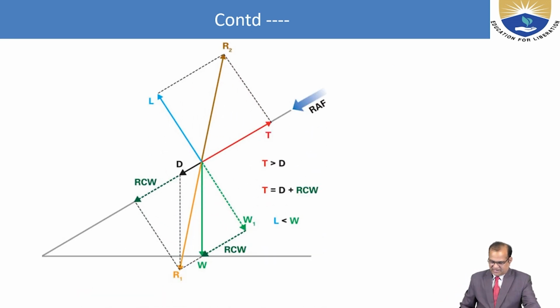Very clear. This slide shows this is your gamma here. It is climbing. This is the relative wind. Initially the weight is here, this green line, but due to the drag, this yellow line will be the net drag.